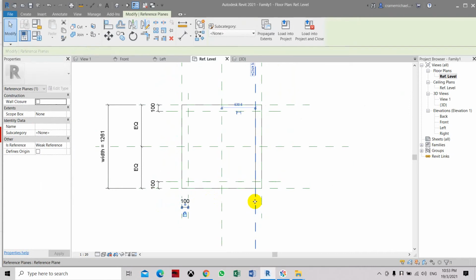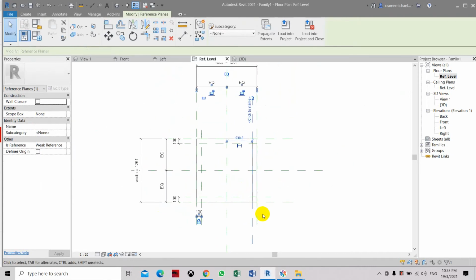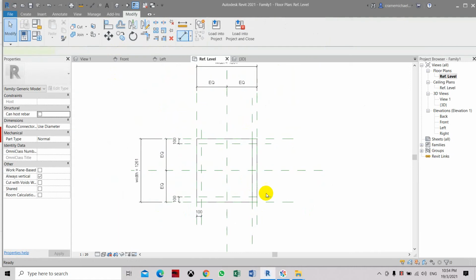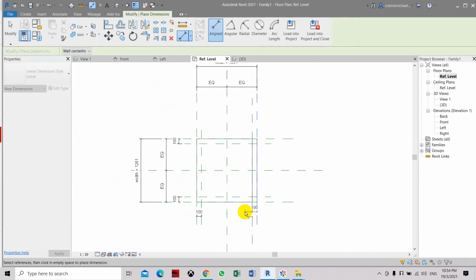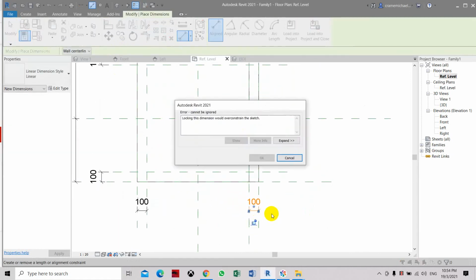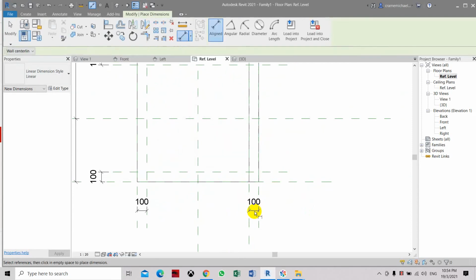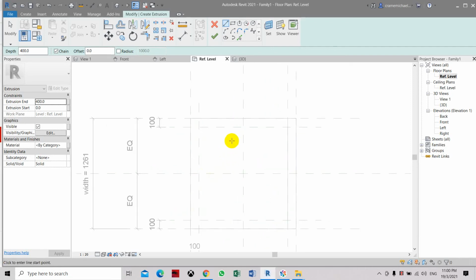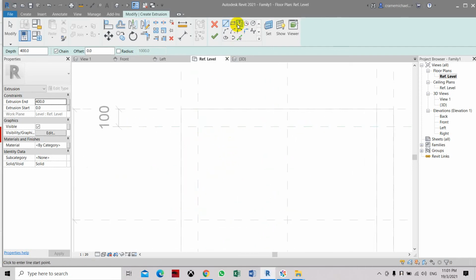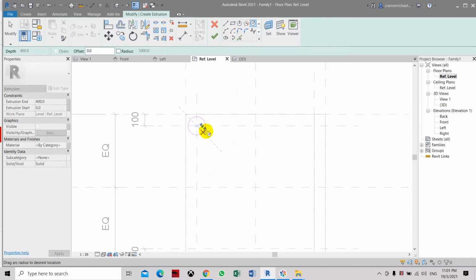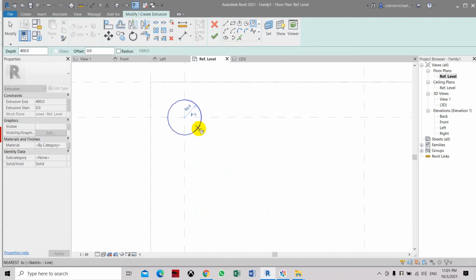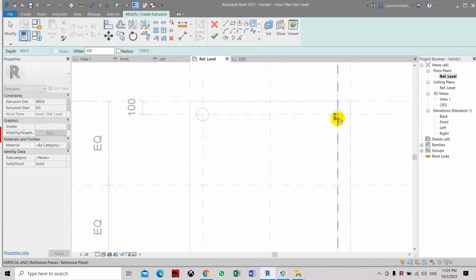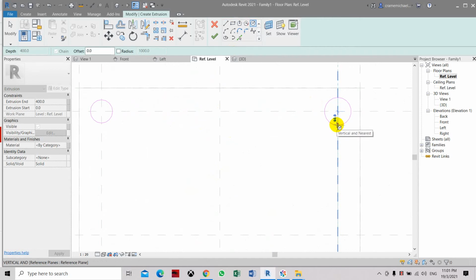Here I think we already locked it, so we have it in position. So let's just make sure it's locked in. It's already constrained on the other side, which is the front wheels. Now let's create the support for this chair. Let's use the circular shape. Let's set it about 50. Then select another support here about 50. You can type it, enter.